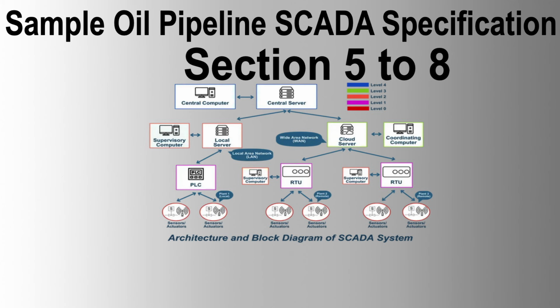7.10 Diagnostic software. 7.10.1 Equipment failures. Diagnostic software provides online and offline test programs to monitor system health and resource utilization, detects system malfunctions, and takes corrective action before affecting control system functions. Provides messages for invalid software operations, system hardware faults, and automatic operator-instigated control system reconfigurations. Maintains summary fault logs for each control system device. Provides failover and restart facilities without affecting real-time operations. Offline diagnostics for detailed tracing of faults.